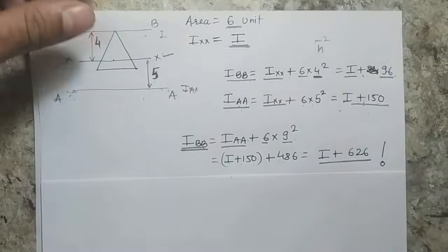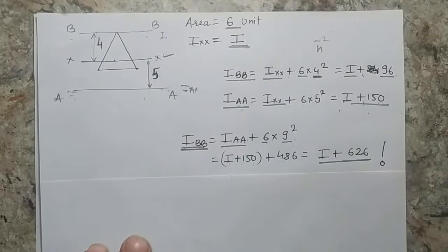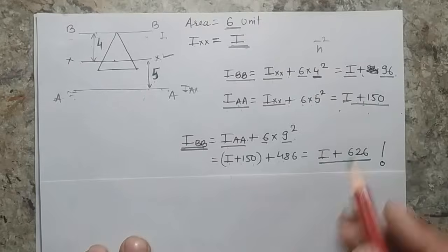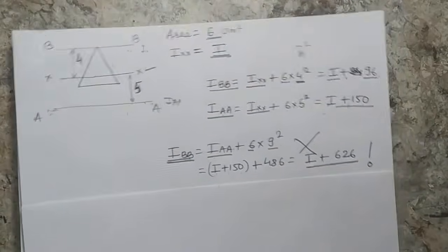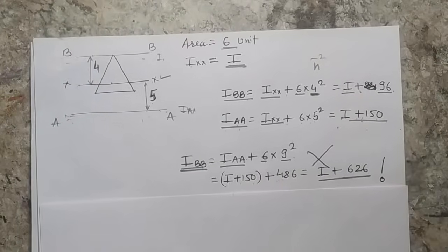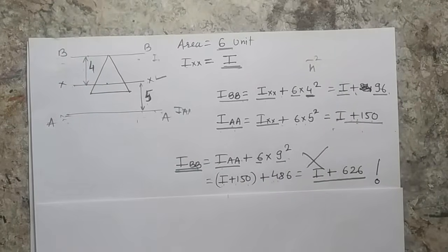So what is the correct value? Is this one correct or that one? Please remember, this is not a correct approach. Whenever you want to shift an axis, you have to use the centroidal axis. You cannot use any other axis, otherwise your answer will not be correct.